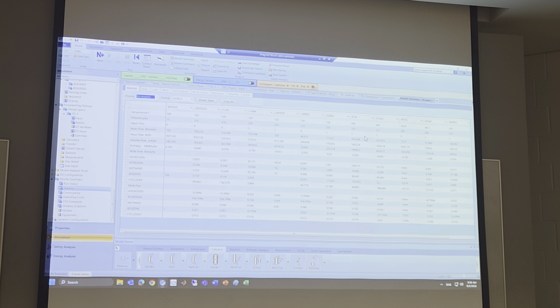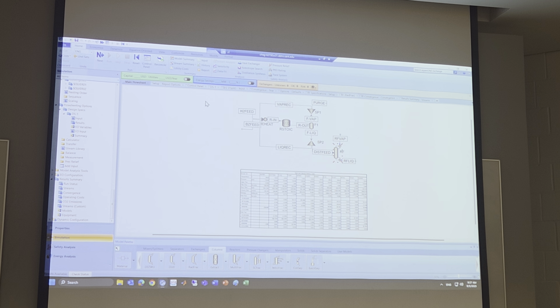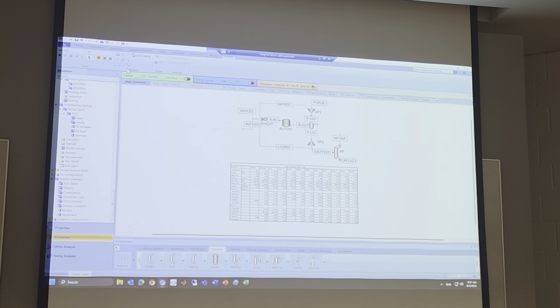You go to stream summary, and we check the liquid stream: 99.9%. We get 78 pound moles per hour of cyclohexane production. Great. When I say homework, you attach this stream table into your flow sheet by clicking this. Okay? And I said red circling, I will show you everything. So what do I mean by red circling?